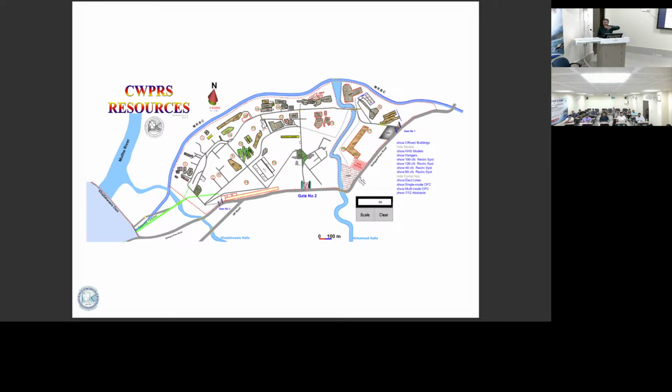There are three systems. One is 120 cusecs of discharge capacity, 100 and 60. So three systems are there, and in each system we have a different pump house. But the main thing is that once we take the discharge, it goes and comes back to the pump house under gravity only. So we don't have to pump anywhere else. At the pump house it again pumps down to the canal system, and it goes on.